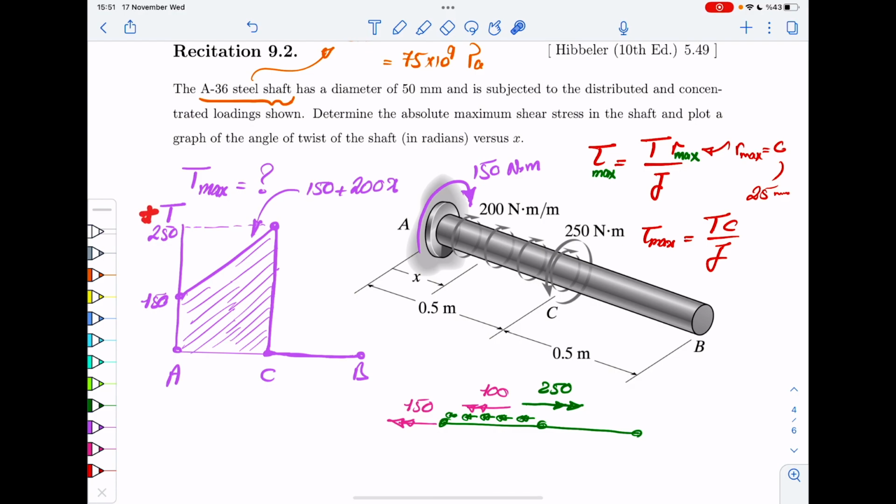Okay? Pay attention that I'm using this with plus sign. So if you look at these, they are clockwise. Okay, so maybe you would be tempted to think these should be minus. But be careful. When I draw this, I am talking about the moment or a torque that you would have inside. Okay, so this is the internal one. It would be the same as if you cut this thing here. If I cut this thing here, what I need inside to cancel the contributions from this would be towards right, and that's what we counted as plus convention. Okay, so the internal torque is counterclockwise